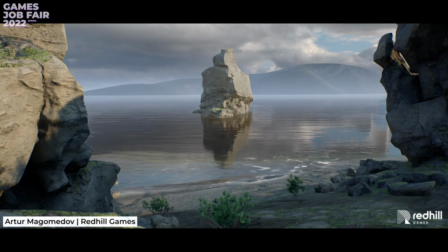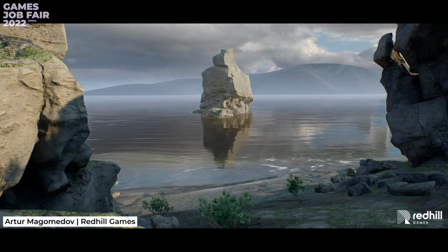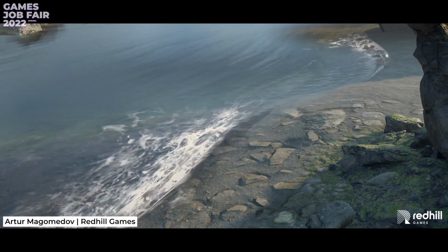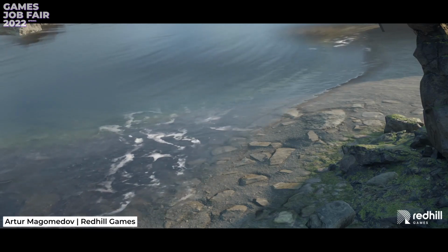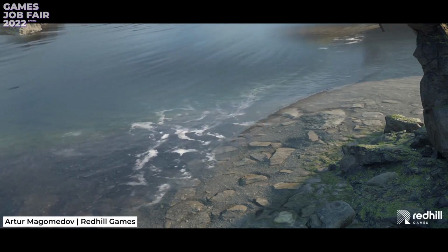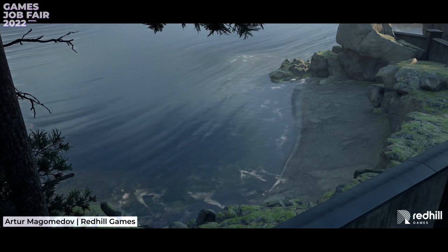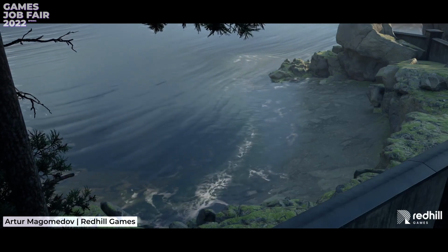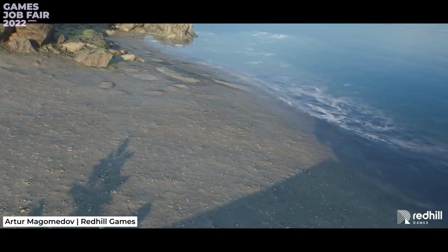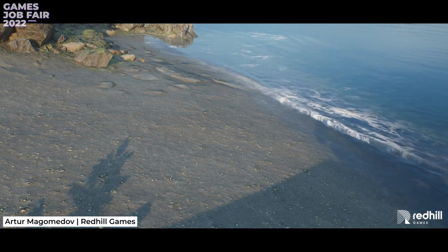As a technical artist, I got a task to make realistic waves for the lake's bay water. The main goals were to make realistic waves that would go up onto the lake shore and flow back. The waves should be 3D and should not fade and stop at the shoreline, so the player doesn't see a constant flat line where the water plane intersects with the terrain. The water surface should blend smoothly with the terrain and other water outside the bay. Waves should have moving form. Ripples should bend and distort with respect to every mesh object that has contact with the water.